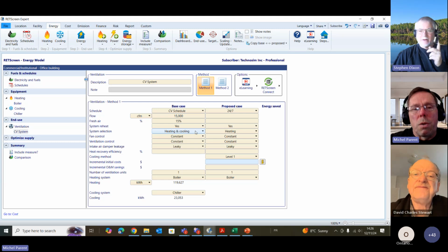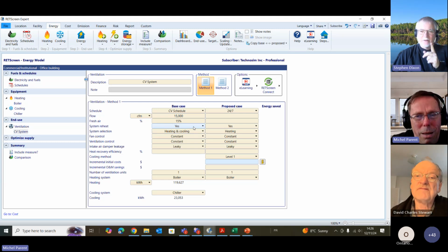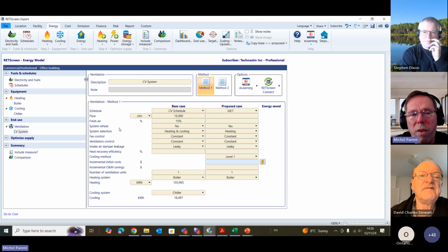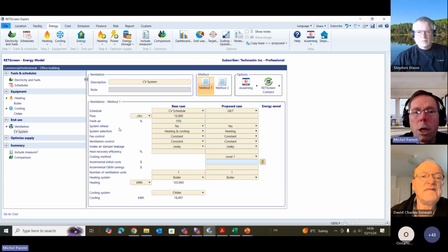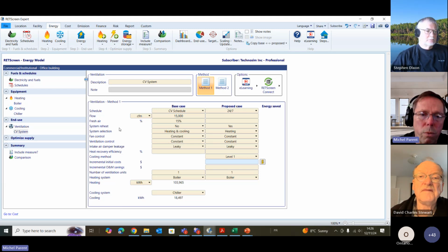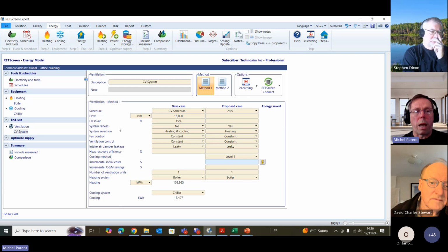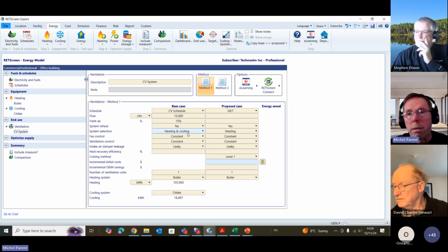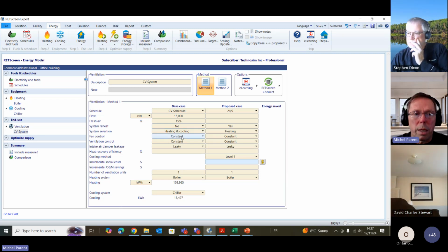Okay. Yeah. So here, if you skipped over reheat, yes, you're going to calculate reheat separately in a more granular method. So we're going to set the reheat to off here, right? No. Exactly. So I would recommend, if you want to maintain flexibility into your reheat calculation, which I strongly recommend that you do, select no for reheat. So we'll select no. I'll show you how to account for reheat in a very flexible manner that will allow you to adjust that rather than use default values. And thank you, Stephen, I forgot about that one there.